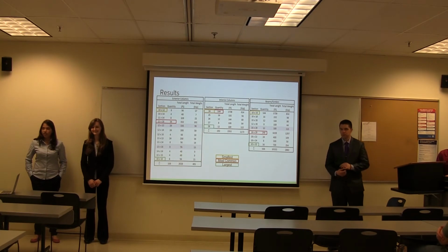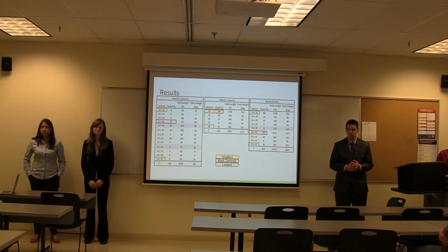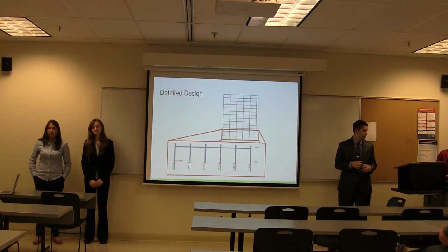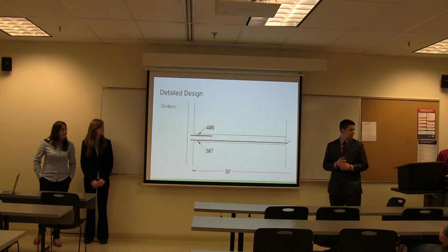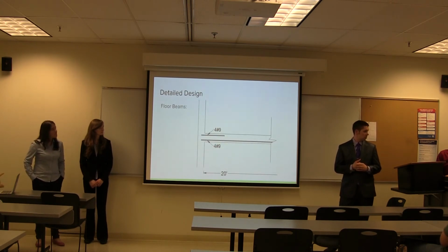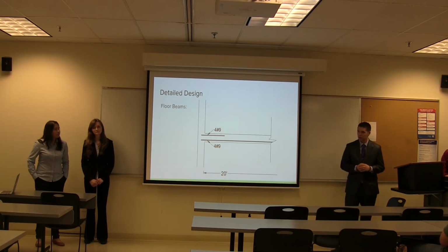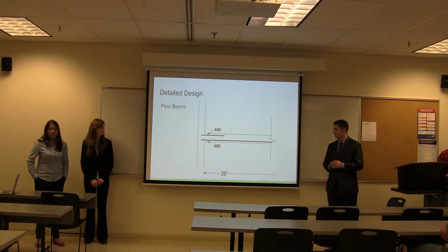One more question from the audience. I had a question. When you were showing the slab coming in and out, I noticed you had number 3. Yeah, this one. You've got 4 number 9s and 4 number 9s, but you actually have much greater moment on the positive side than the negative side. Could you have gotten away with less steel on the bottom? Yes, you can. I want to elaborate on this one.